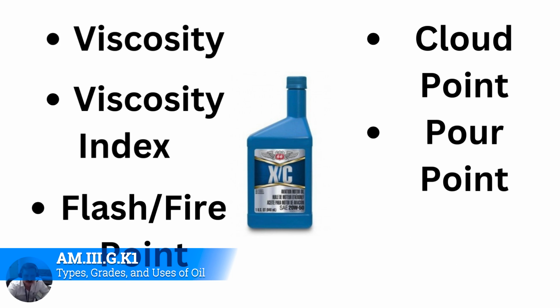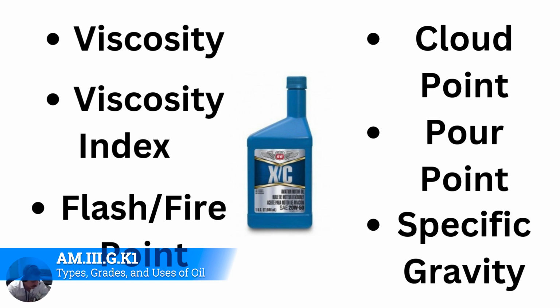Okay, now let's talk about specific gravity. Specific gravity is a comparison of the weight of a substance to an equal volume of distilled water at a specified temperature. As an example, water weighs about 8 pounds per gallon. Oil with a specific gravity of 0.9 would weigh 7.2 pounds per gallon. So specific gravity is nothing more than a reference: how heavy is it per gallon? This comes into effect when you're looking at weight and balance. We start talking about how much the usable oil weighs or the unusable oil weighs, and how much the oil weighs when it comes into it.